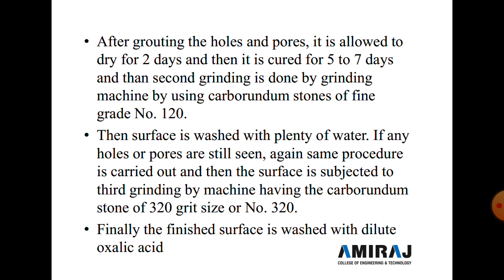subjected to third grinding with a carborundum stone of 320 grit size, number 320. And now, finally, to finish, the surface is washed with diluted oxalic acid. So here